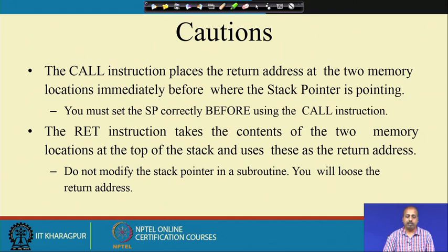If by mistake the stack pointer contains some garbage value, then the program counter value will be saved onto that memory location. So, it is the user's responsibility to ensure that the stack pointer is pointing to a valid memory address which is not used for any other purpose, and the return address can really be saved there and retrieved later.